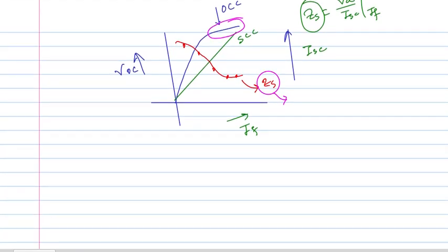Now that Zs is known, using a multimeter we can find out the per phase armature resistance. Then if Ra is known by measuring it with a multimeter, Xs is nothing but the square root of Zs squared minus Ra squared. So we get the value of this Xs.